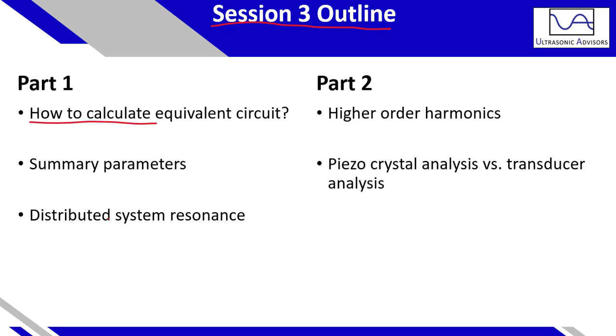I'll first describe how to calculate the equivalent circuit of a piezo resonator. So we have our capacitor in parallel with an LCR circuit representing the electromechanical resonance, and the parallel capacitor then describes the intrinsic capacitance, or the static capacitance, of the piezo element.